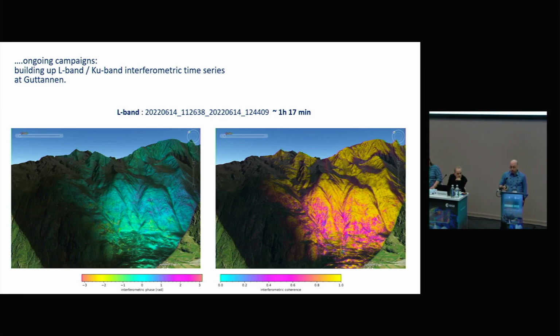Here you see the coherence and the phase on the left-hand side. Again, the phase is not further treated, so this is just topography corrected, processed directly to the digital elevation model using a time domain back projection approach, using accurate navigation. So this is basically what comes out of that, doing just the interferogram, with no other phase corrections applied so far.